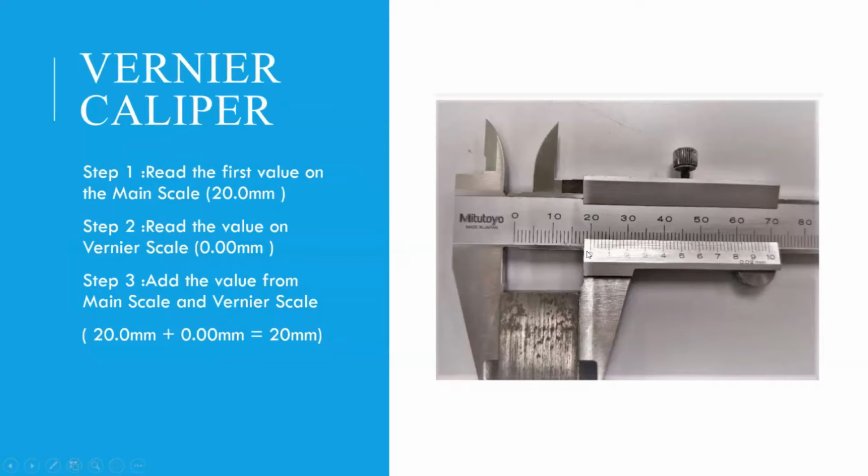From this image, we can see that the 0 is aligned to the 20. So we take 0 mm. And lastly, step 3, add the value from the main scale and vernier scale, which is 20 mm plus 0 mm equal to 20 mm.